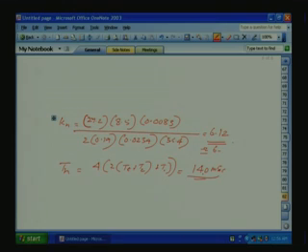Speed controller, again the same way. We want the speed loop reference to be filtered, to avoid the overshoot from the numerator, which we found is 1 plus TNS times 1 plus T1S.